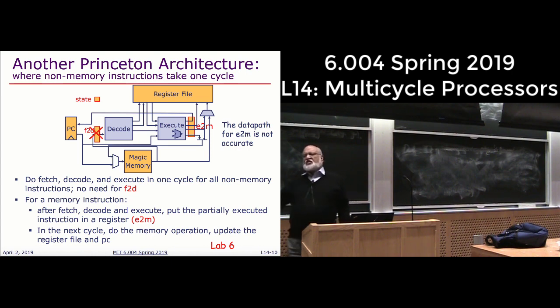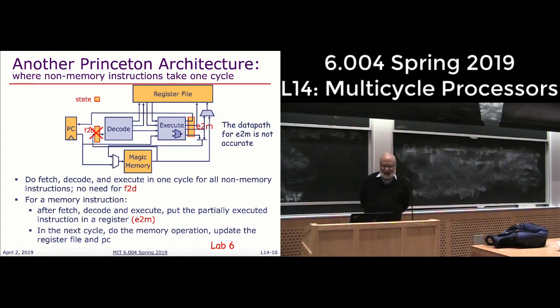But most of the time, we don't store anything in that register. We will be writing into that register conditionally, only if the instruction you want to execute is a load or store instruction. In the next cycle, we'll do the memory operation on this. The data paths for EM are not accurate. I have to always remind you that these pictures are just to help us understand conceptually what's going on.